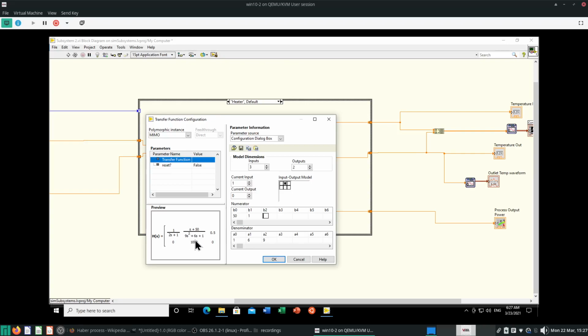Now, to make sure that there are no oscillations, the bottom is actually a second order sort of process, because of course electrical power will translate into heater power, and heater power will actually take some time to heat up the tank, and then have the output. So the bottom, I have a second order process. It's actually 1 plus 3s whole thing squared. So that's 9s squared plus 6s plus 1. Yeah, that's what I have in this transfer function. So arbitrary second order process with 1 0 on top. And then I have a transfer function for noise. It's just a 0.5 gain, that's all.